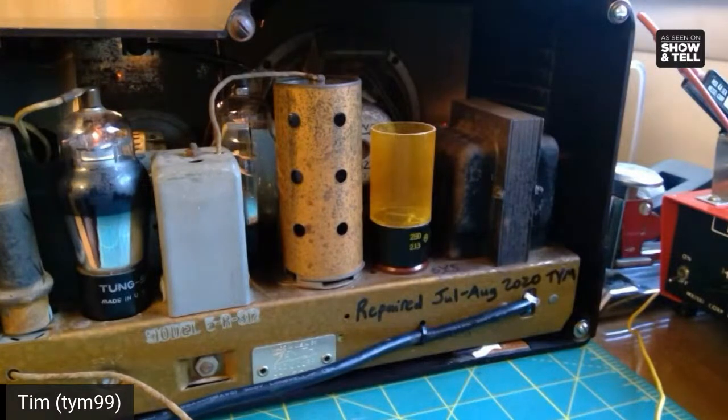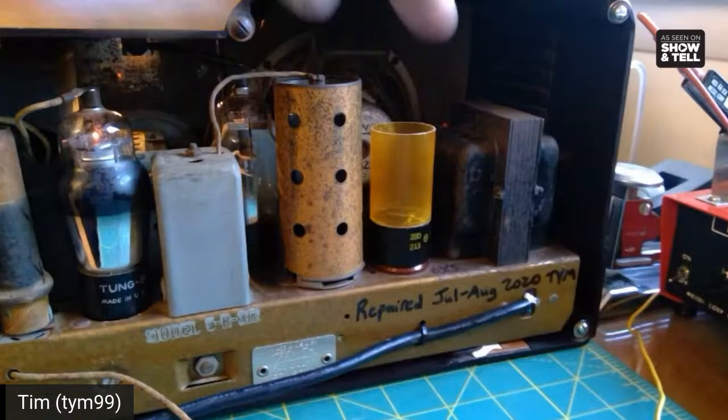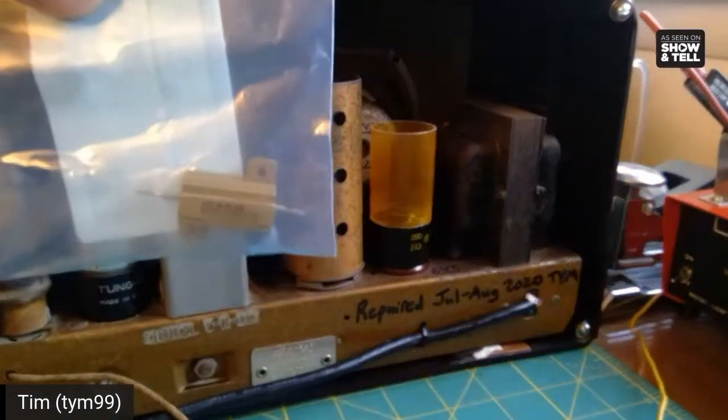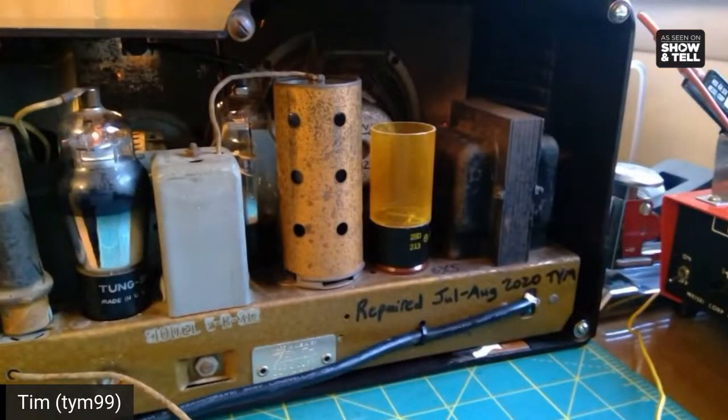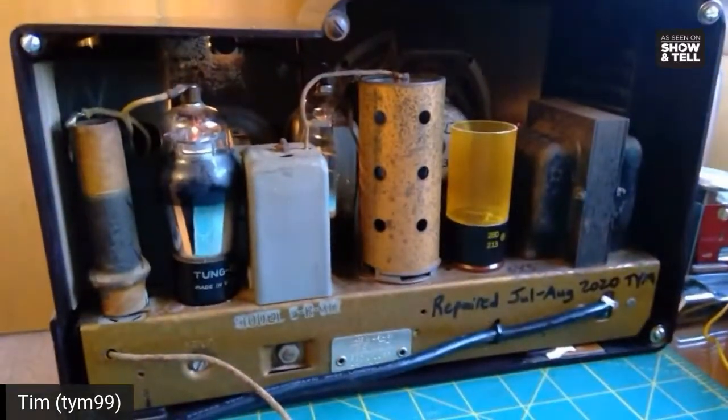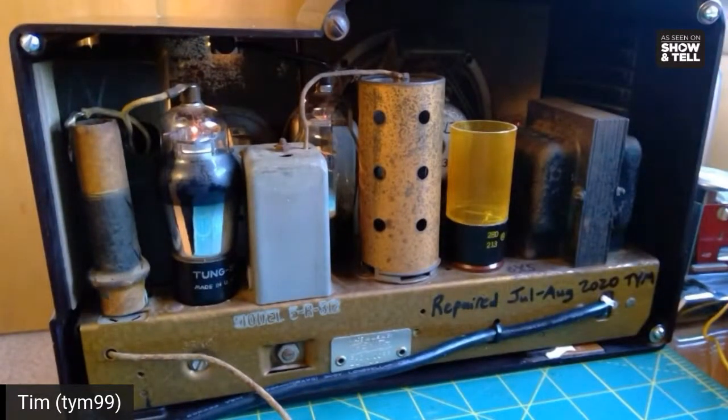It's actually the base of the rectifier tube. The rectifier was shorted, but it could be replaced with a couple of diodes and a resistor to give the proper voltage drop for the old rectifier tube. And I just built that into the base there. And then the other thing is, from our friends at Digi-Key, I got some power resistors, and I used those to drop the line voltage from today's 120 to 125 volts in the US down to about 115, which was kind of the standard in the US a long time ago in the 30s and 40s.